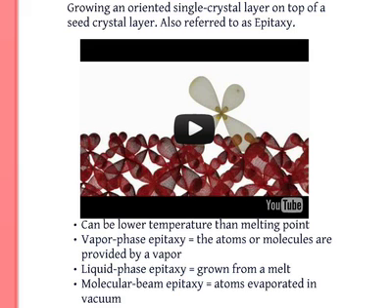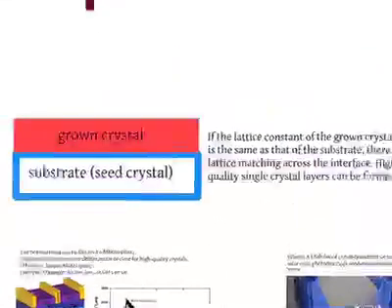Those bonds are where the next silicon atom can fall. So you imagine a seed layer with dangling bonds. If you introduce atoms with the right conditions, it can form a single crystal layer on top. That's epitaxial growth, pretty much. And that's what the video shows, actually. So you can watch it in your own time.